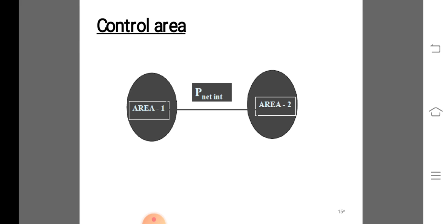While the initial governor response is the same as for the previous case, the action of the controller in B will force the generation in area B to absorb the load increment in area A. When the controller begins to act at time 3, the governor characteristic is shifted parallel to itself in B till the entire load increment in A is absorbed by B and the frequency is restored to normal.